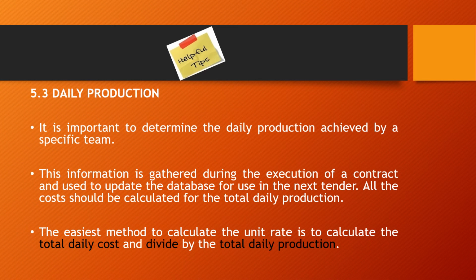So you've always got to have a record of your daily productions, even if you are digging trenches. Say you're digging a trench on soft soil using a TLB. You've got to know how many meters a day the TLB excavates on a certain width of a trench.